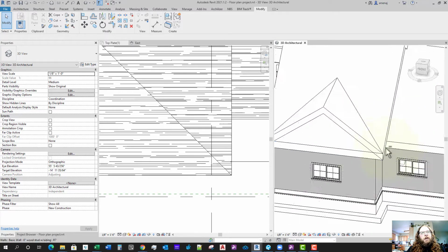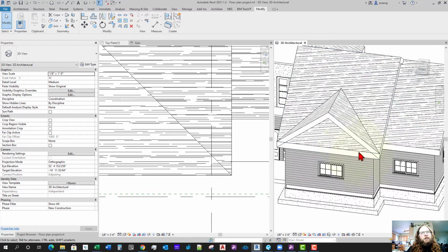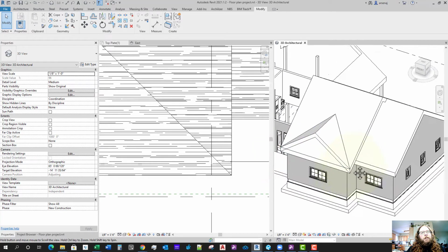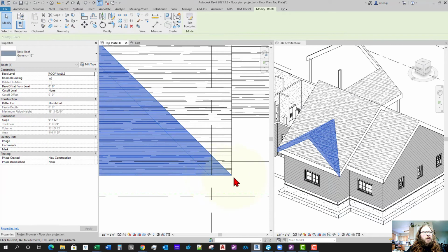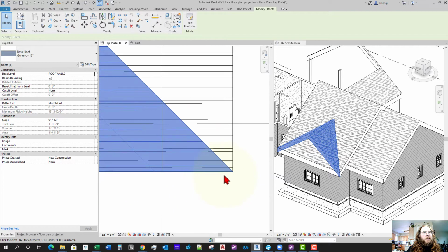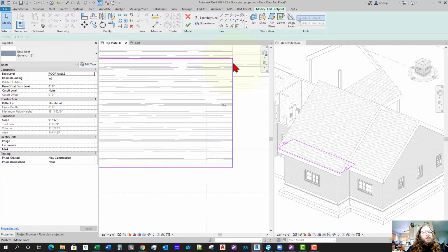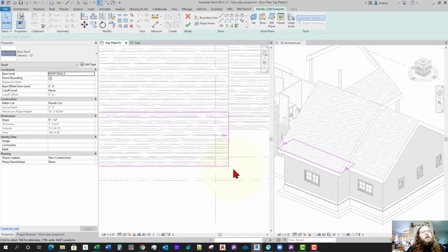It's an interesting issue with Revit, and I'm not sure exactly why it does that, but I think it's just because it's over constraining the geometry, because this outside roof is actually a boundary line. I think what happens is it makes this boundary line too small. Even though it hasn't changed our boundary line, when we hit that join, it's manually making this boundary come all the way out to here and then up, and so it's not letting it join.